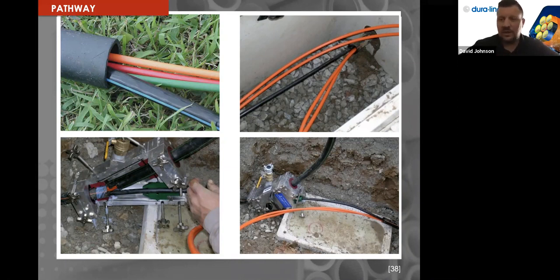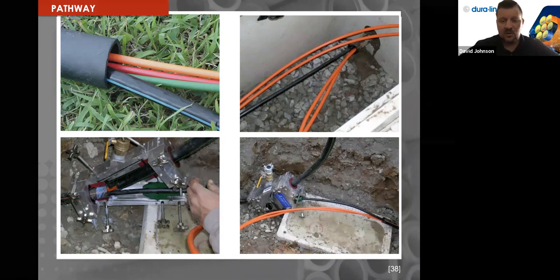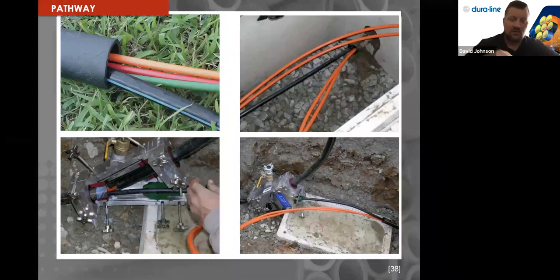Whereas if you're pulling, you're going wherever that cable's going and wherever it directs you, depending on how you're pulling the fiber in. You can see here on the bottom two photos, there's a Y block, and we'll talk about what that Y block does in a second. But really what it does is it separates that existing fiber cable and creates a pathway for those microducts to go into the existing duct, allowing us to hold air pressure and push it through the existing conduit, so we can float those microducts over top of the existing fiber.